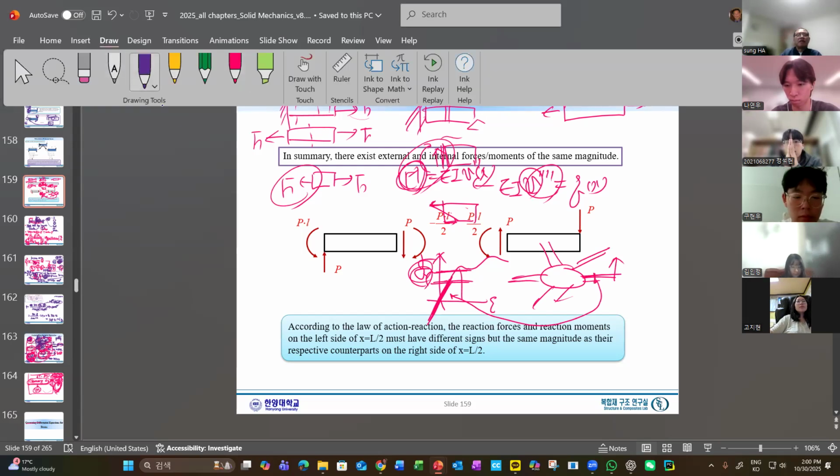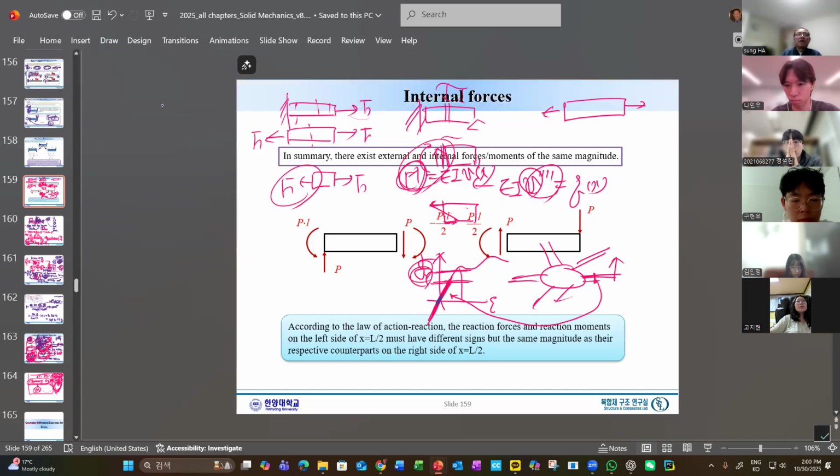Design-wise, let's say the stress will be very small here, only this part. This is not a good design. Why? Because we are wasting the material. And if we have a very thick section, then the stress will be very small, only a small portion of the material capability. Then it's a bad design. You as an engineer are not a good engineer.